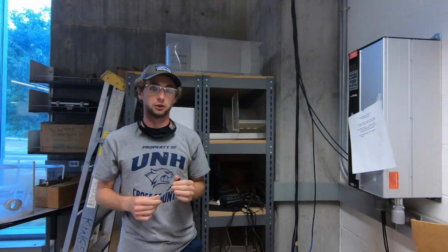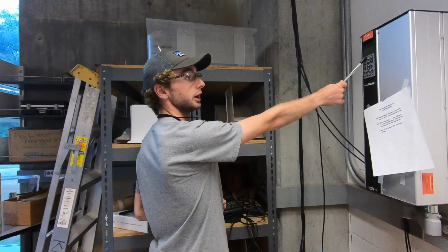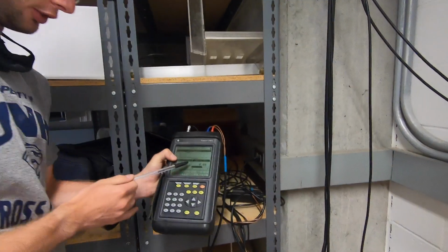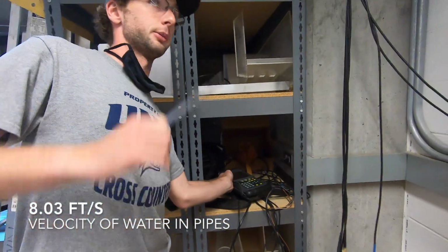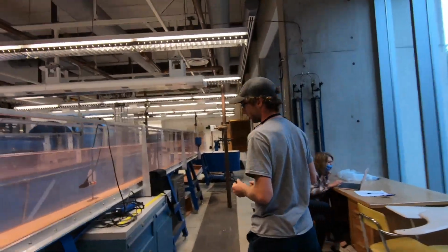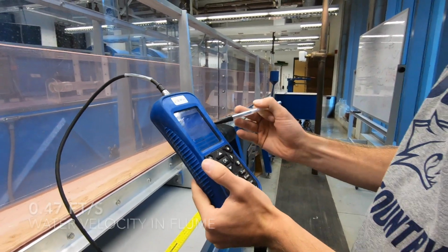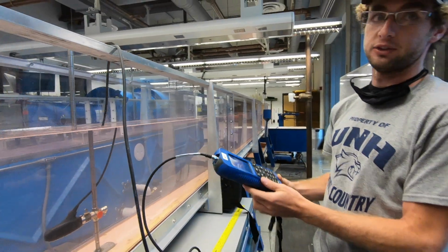Now we're going to do trial 2 of part 1. So for this trial, we have the pump running at 48%. Our velocity is currently 8.03 feet per second in the piping. For the Marsh-McBurney flow meter, the water is fluctuating at about 0.47 to 0.5, so call it 0.47 feet per second.